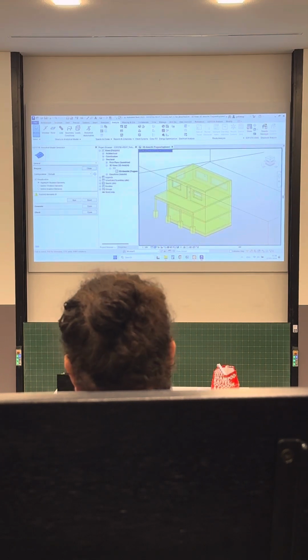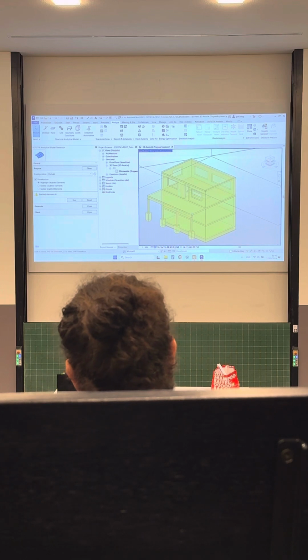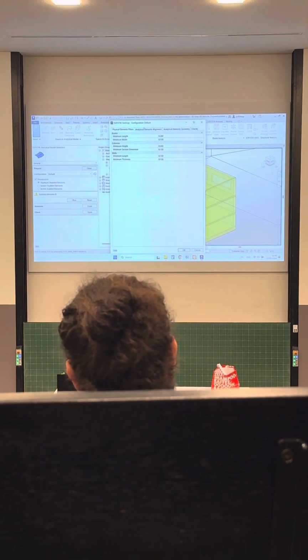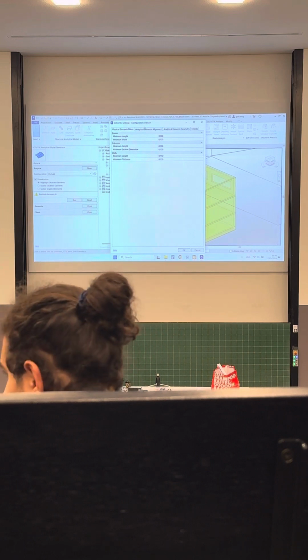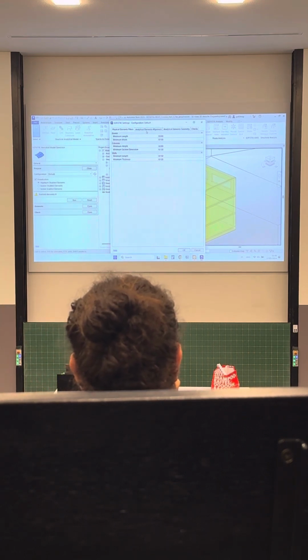And it's showing us which element it will transfer into the structural, because as I said, we don't need all this extra information on the furniture, on the doors. We will just use our load-bearing elements for structural model. And you can also configure your elements that, for example, it will read beams if it's minimum length of 30 centimeters, or the column should be minimum 30 centimeters. So you can all configure here.